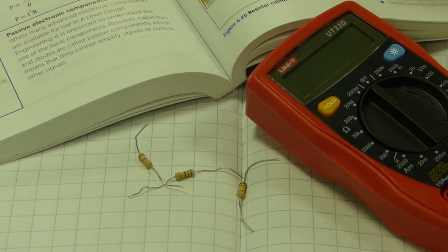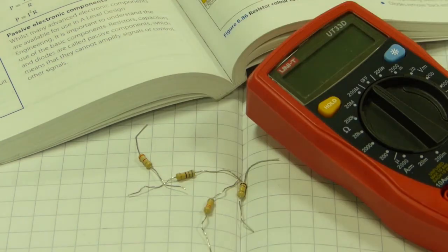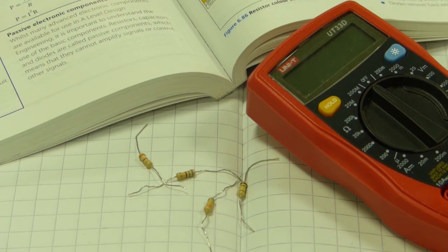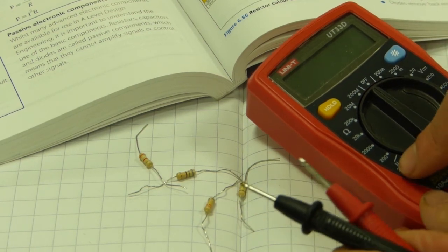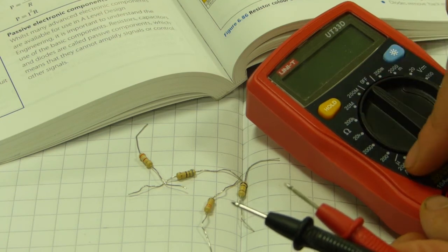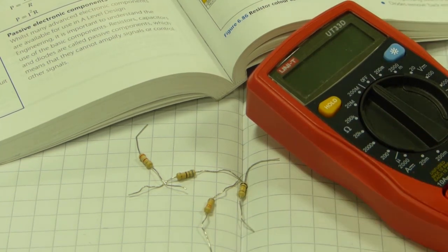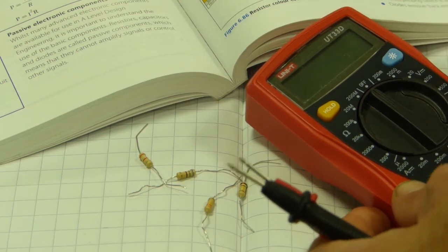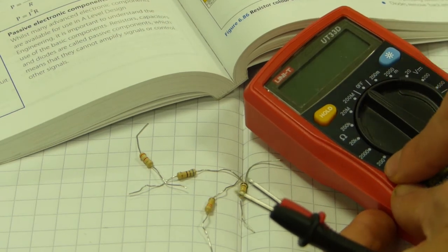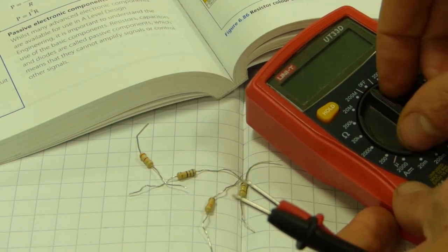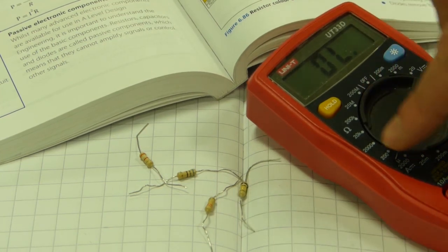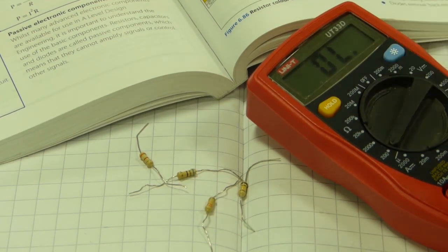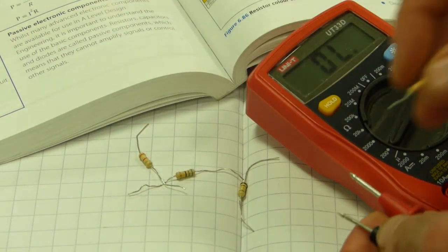So in addition to using colour charts, the resistor tables, you should be able to use a multimeter as well. Being named a multimeter, it measures a multitude of different electrical things, one of which is resistance. In the case of this budget one, by the way, these are very good and indispensable if you want to do electronics yourself. They're not expensive, but a nice robust multimeter. It goes from 200 up to 200 million ohms. With these more budget ones, you do have to select the range manually. The more expensive ones will just automatically choose the range.